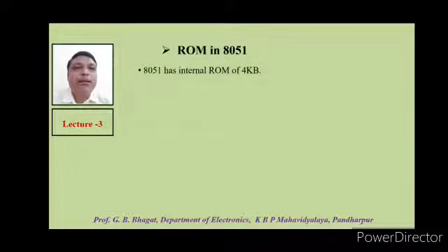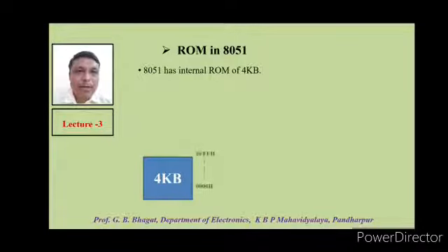8051 has ROM of size 4 KB. This 4 KB of ROM is addressed from 0000H to 0FFFH. This is the internal ROM of the controller.